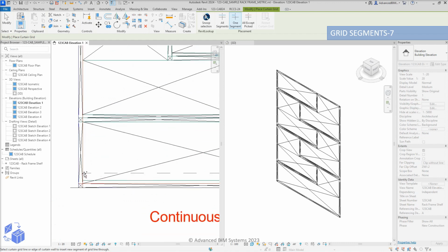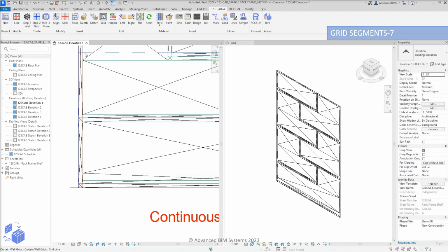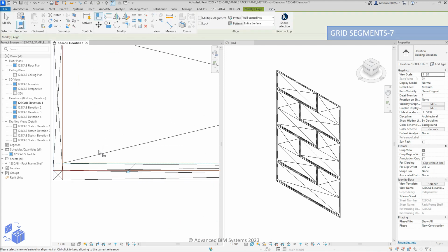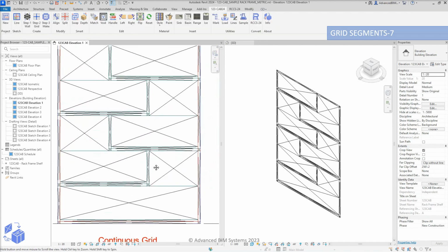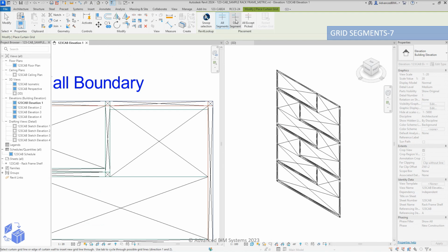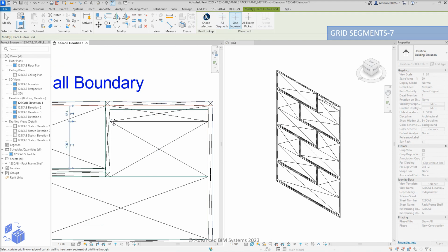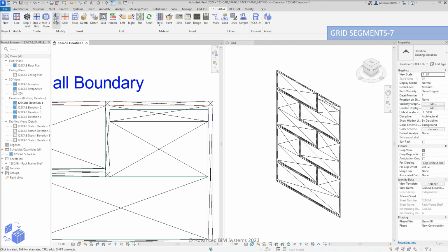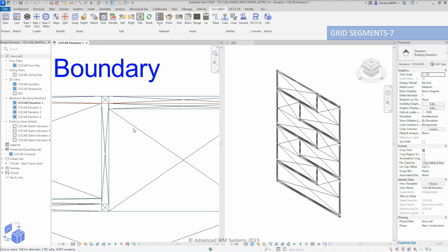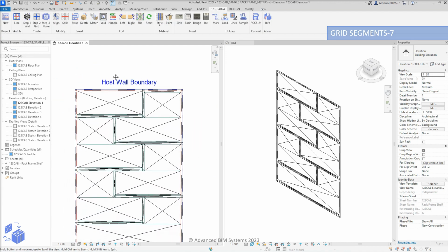Finally, let's add both the base shelf grid, as well as the topmost shelf grid, to this design. The Make function AI will automatically locate and resize shelving to fit in between the various horizontal space frame elements. The topmost shelf grid must always be placed below the topmost space frame. The Make function AI will recognize this as the topmost shelf and automatically move it upward to fit in between the topmost space frame elements.